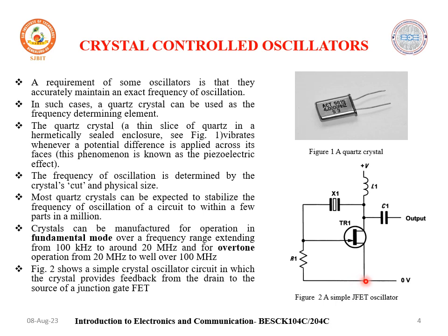Consider when an AC voltage is applied across the crystal, it starts vibrating at its resonant frequency and it looks like an equivalent tuned circuit. When the crystal is mounted across the AC source, and if it is not vibrating, it is equivalent to a capacitance. When it vibrates, it acts like a tuned RLC circuit.